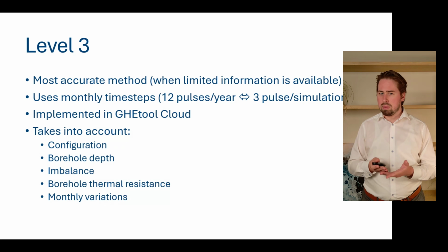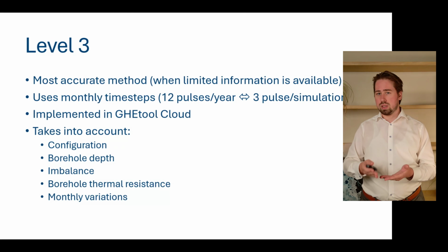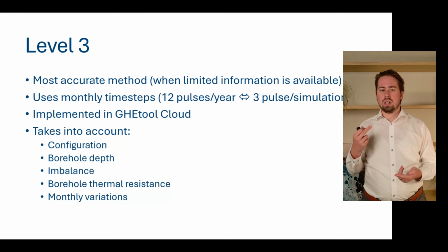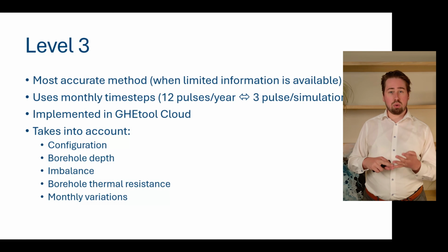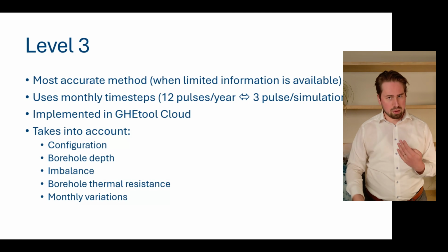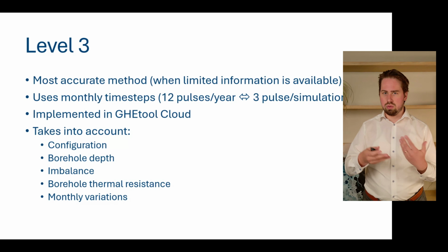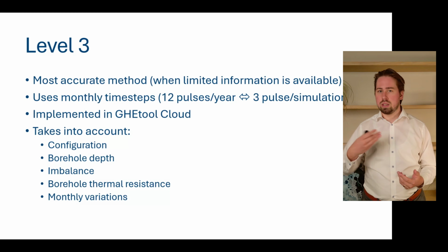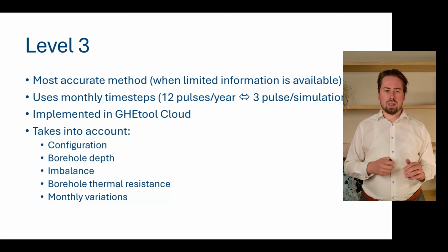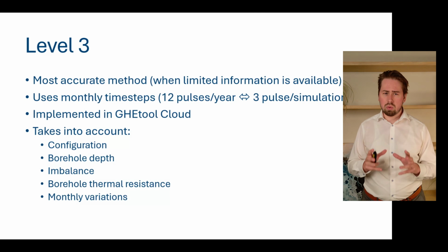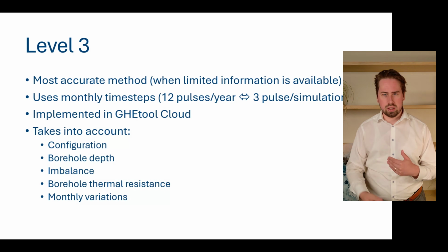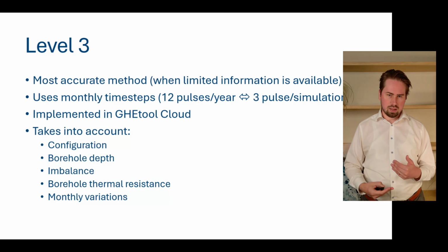And this method is implemented in GHEtool Cloud, and what is interesting is that we again consider configuration, borehole depth, imbalance, borehole resistance, now changing at every month in heating and cooling, due to the fact that we use variable flow rate, variable fluid properties. We discussed that already a couple of times in the previous parts. But now we also can consider the monthly variation. There is a monthly profile behind it.